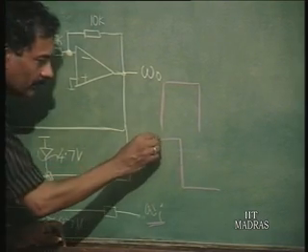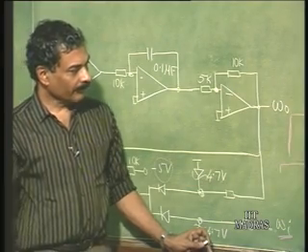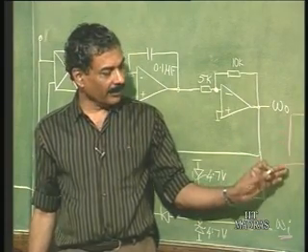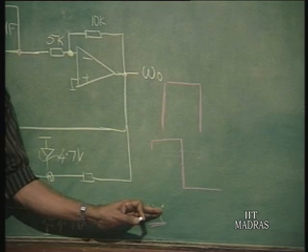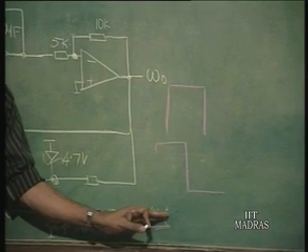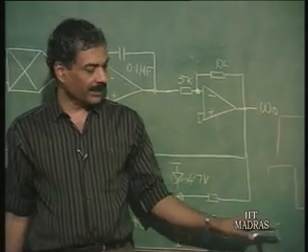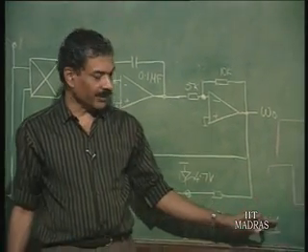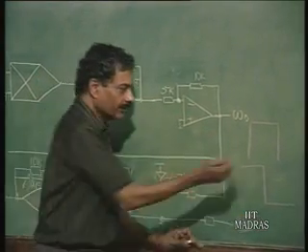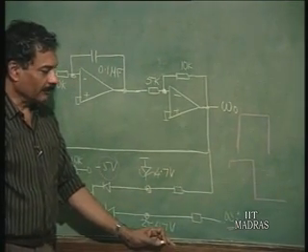Okay. So, this demonstration is going to be done first, and then we will apply. First you will manually see that when this is manually varied, this is going to track. Then we will make this vary automatically, that means we will apply an FM waveform here. Okay. So, around this carrier, which is close to the free running frequency, we apply a modulating frequency to the carrier. So, we get an FM, okay, which is modulated by a sinusoid. Okay. So, then you will see that this is also going to follow this in the same fashion. You can see the edge tracking, okay, and keeping itself under lock all the time.